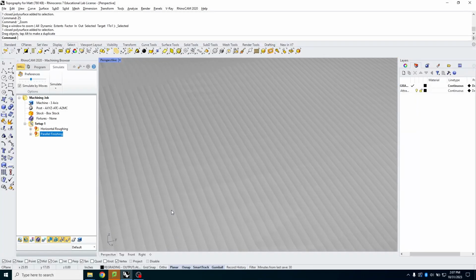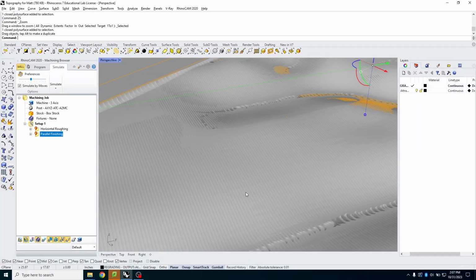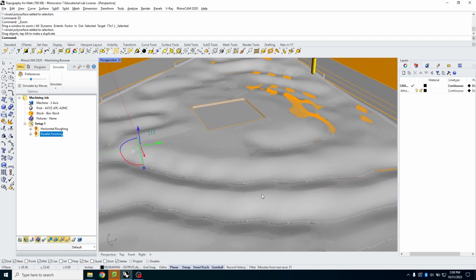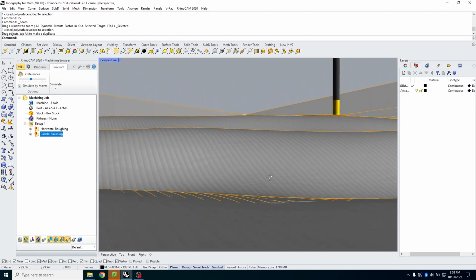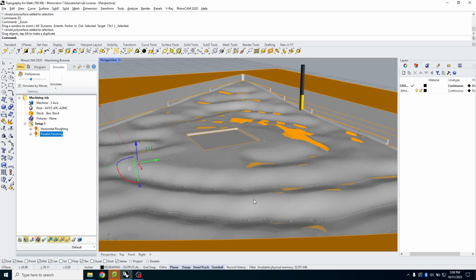Granted, we're zooming in, so if this is 15% of 3/8, I guess 4 or 5 of them should be 3/8 of an inch. We're never going to see it this close, but this is an almost negligible level of step over. Everything looks very flat and even. You'll need a light sanding.